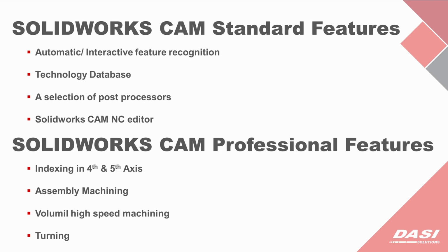So that's what you will get with the upgrade to CAM Professional. In all of the cases, though, it is important to note that SOLIDWORKS CAM is only 2.5 axis. There are some 3-axis operations you can apply, but they aren't going to do any simultaneous 3-axis machining. So you can do area clearance and step down for clearing out 3D features, but you're not going to be able to then go back over and do a nice clearance path, a nice contouring path for a 3D surface.